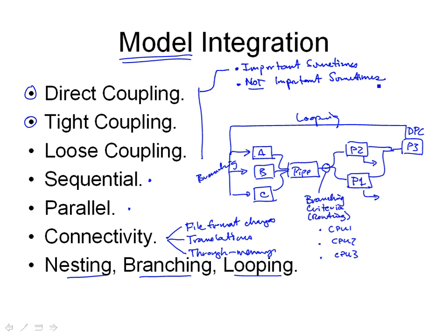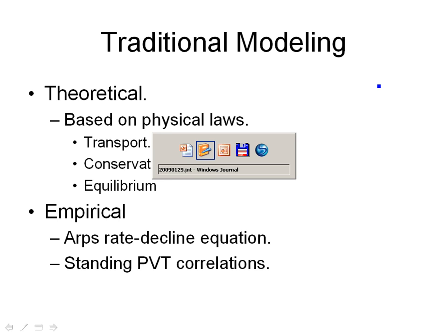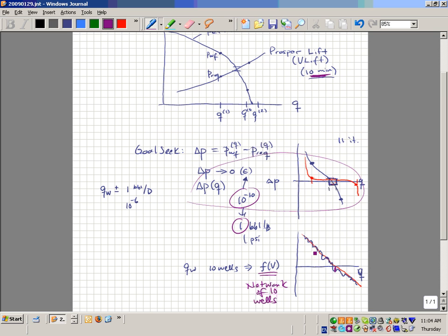Yeah, and that's really what we were talking about on this other slide: the objective function, your f that you're creating in an integrated modeling environment, is probably not smooth as a function of all of the variables you're changing, almost very seldom. If it's not smooth because of looser coupling, or because one model doesn't converge very accurately, there may just be one model out there that has sloppy tolerances. You have no control over it.